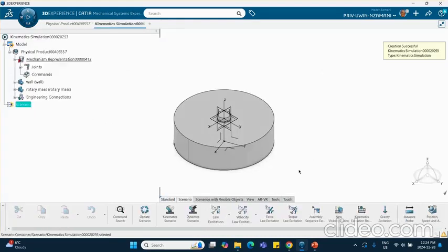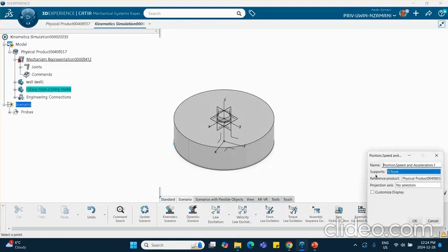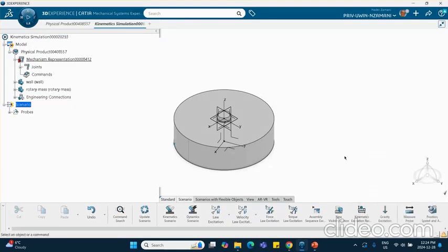Simulation is created. Now let's create our probe here. The probe, that's why I created a point there, because if I want to, for example, see velocity here, I can use that. Good. And now there is no need to do any of these excitations, because the fact that we offset that thing by 20 degrees will actually create a restoring force, restoring torque, which makes motion possible.